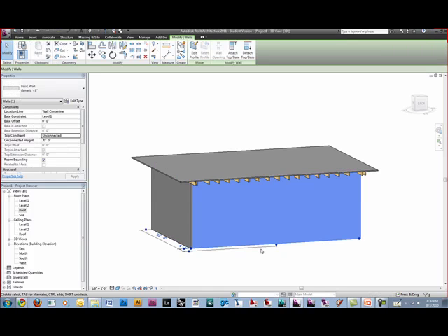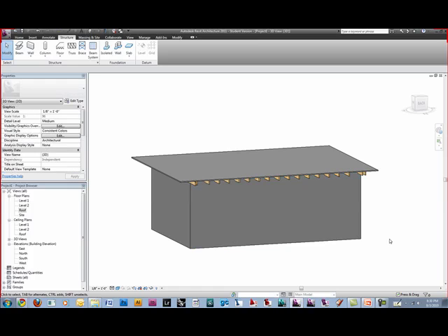And then we're going to show you how to create what we're calling custom windows. In one of our screencast videos, we show you how to create custom windows, triangular and circular shaped windows. We're going to do an L-shaped window. You create those the same way. There are two different ways to go about it: placing a curtain wall into an existing wall, and having a curtain wall and then placing a generic wall into that curtain system. So two different ways of thinking about it.